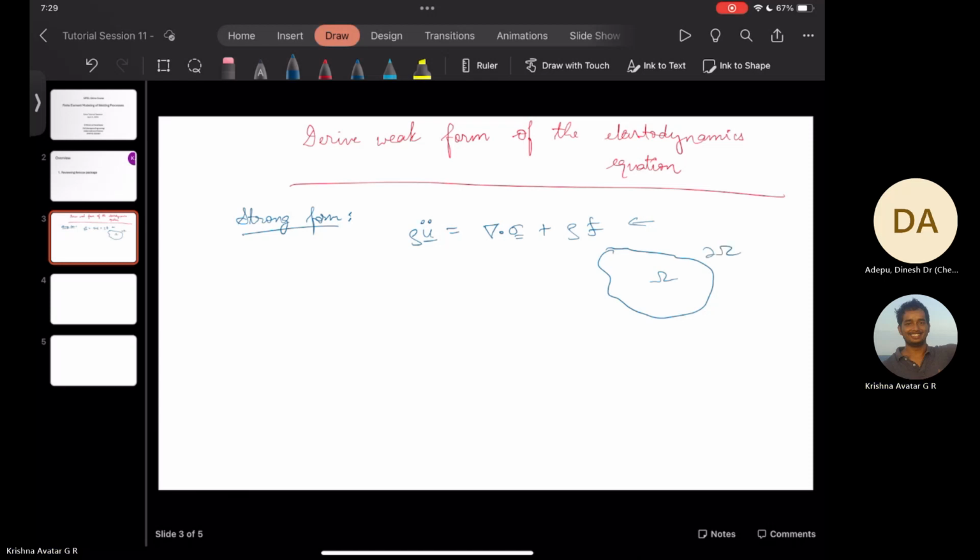partial omega, then say on a certain region of the surface we are having some tractions. So this will be the area in which we are applying some traction T vector. And say there is also a distributed load being applied, so F vector. And then on this segment, we will have some displacement boundary conditions. So we'll call it partial omega U.